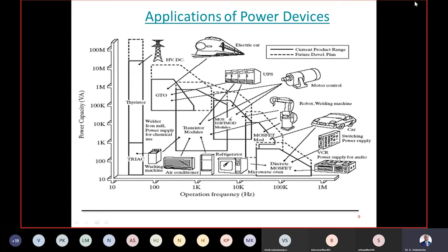So we had been to Power Grid Corporation of India Limited, PGCIL Kolar. There was a power line coming from Orissa Talcher, where a 400 kV DC line is there, and their DC is converted to AC using inverter circuits made up of thyristor family members. They have a huge building where only thyristors are installed. That's one of the grids on the southern side. The HVDC and HVAC handle very huge power. There I cannot switch at high frequency; I can only handle very low frequency because I'm handling more power.